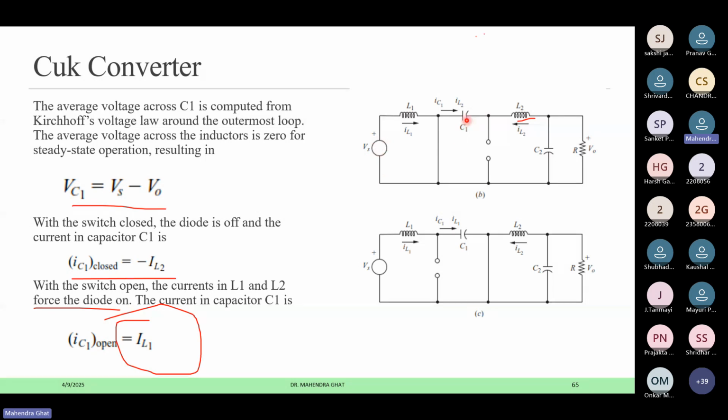But the capacitor and inductors do not operate like that. For on time they store the energy, and for off time they release it. Continuously they are not either storing or releasing the energy. So if the battery is considered here, over the cycle there will be no change in the charge.